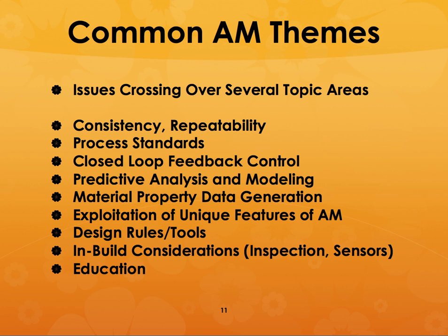So for that, you need to create process standards. You need to have sensors to give you closed loop feedback. So if you make one layer and during that layering process, you find that, hey, there are some areas in this layer that are missing the material, before the next layer is laid down on top of that layer, can you go back and repair that area before it moves on to the next layer?